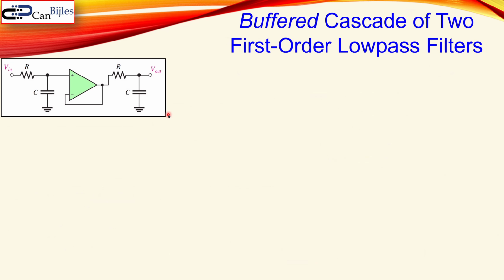Now, when you do a different configuration, which is buffered, we actually have the same circuit, only with this unity gain feedback op-amp circuit here. So this is a voltage follower or a buffer. What happens in this case? Now, this is a simpler circuit. Now we can isolate the left and the right RC circuit, and our transfer function is like so. I call it B for buffered.